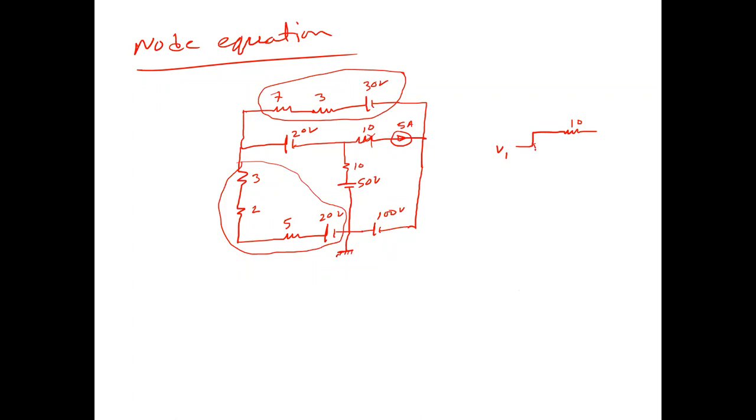And this is our current, and the current flows from minus to plus, so the current flows right to left. This is called source conversion. Now our current in this portion, anybody? 3. Good, 3 ampere. So this part is finished.